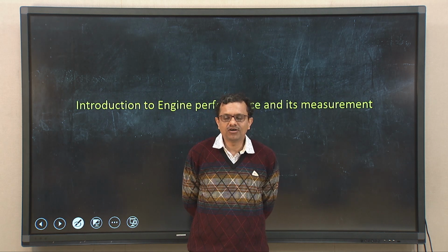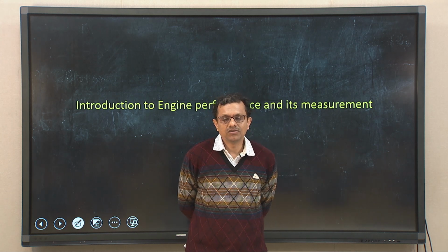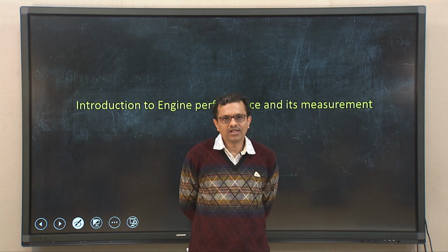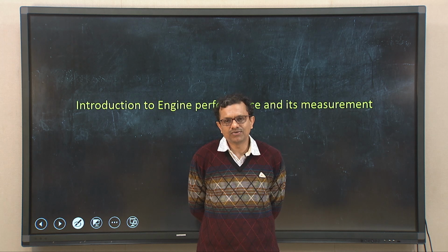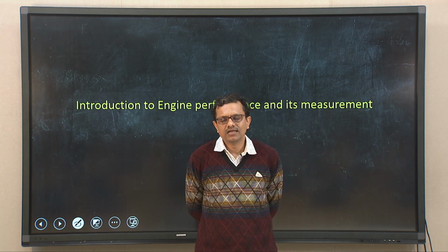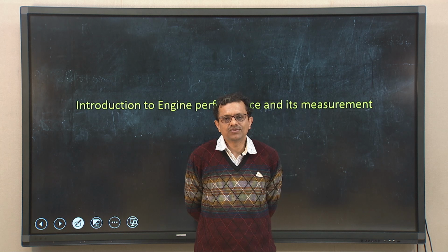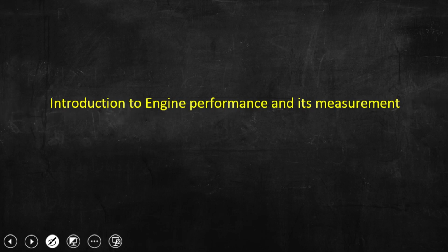But what we have understood is that the functionality of the electronic control unit depends on the input from several sensors, and all these sensors are responsible to give some feedback to the electronic control unit. Receiving feedback, the electronic control unit or ECU directs several parts of the engine to have adequate, or I should say stoichiometric, air fuel ratio to be drawn into the engine cylinder.